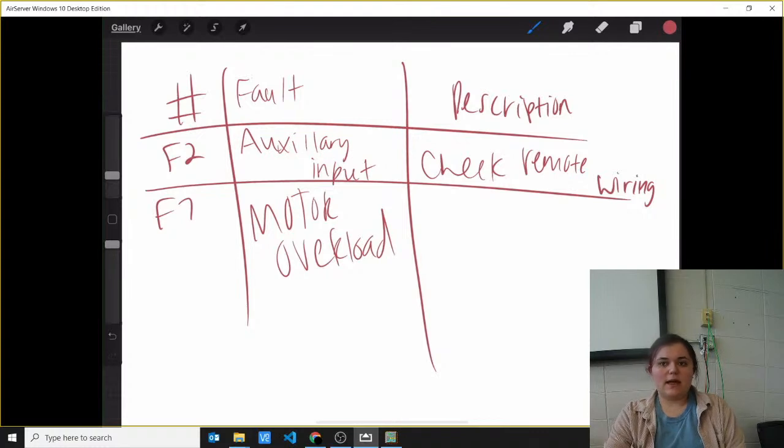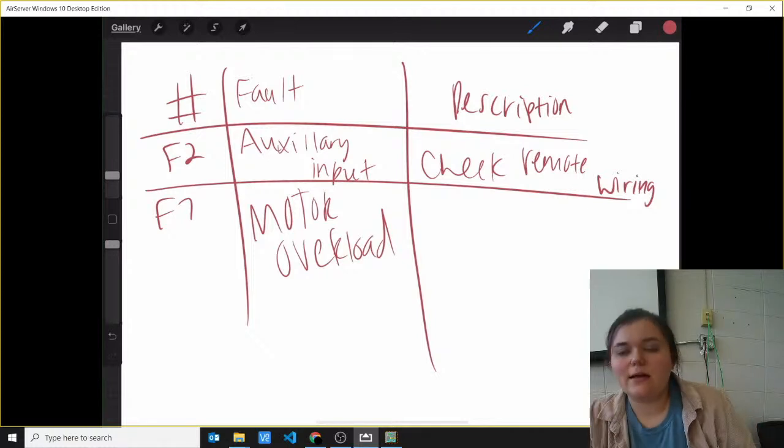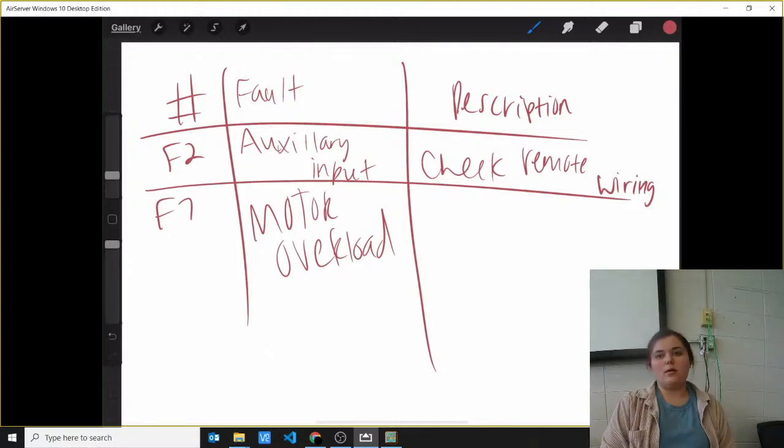So do you kind of get it? It does make your job easier. It kind of sounds complicated, but it seems pretty simple compared to wiring up a contactor. Once you get that contactor wired up, you don't have to wire it up 50 million times for 50 different applications. Once you get it wired up, you literally can control everything through logic and VFDs and stuff like that.